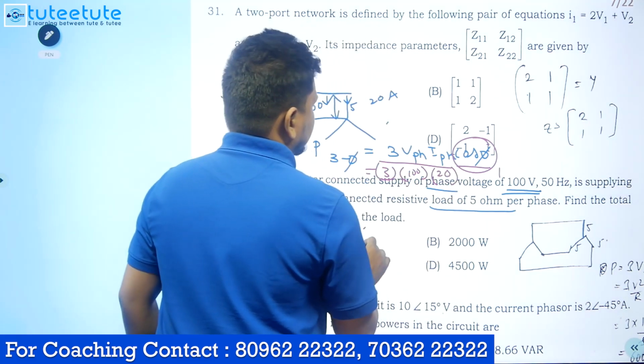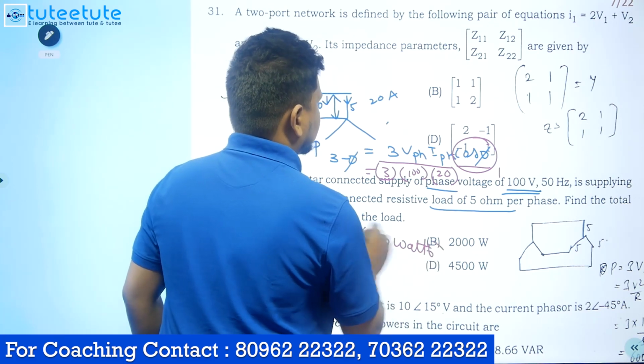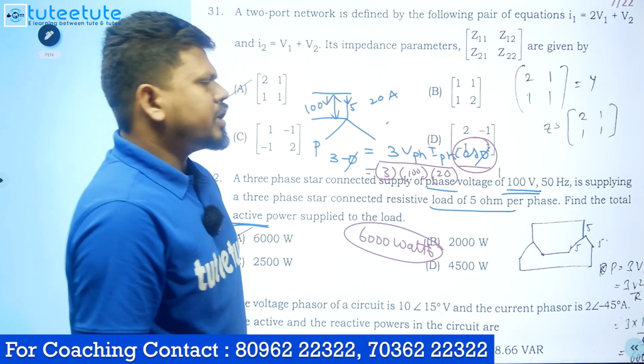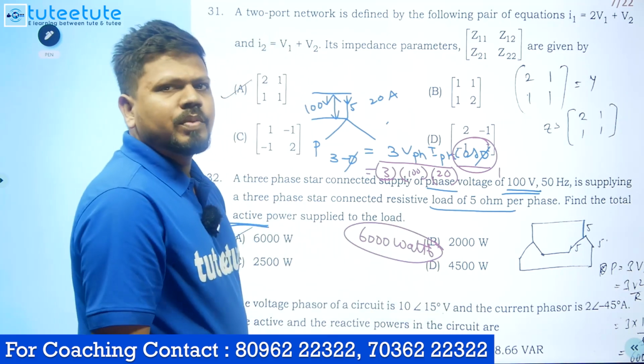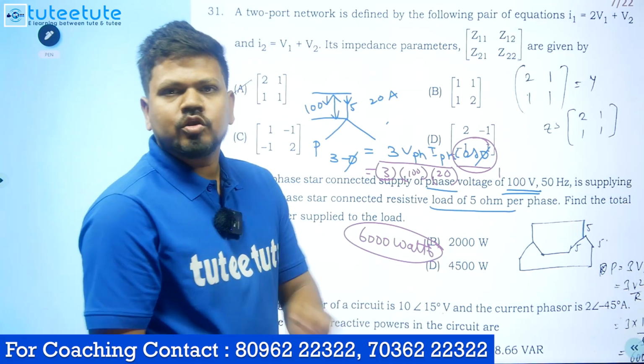Okay, so you will get 6000 watts. That's the answer. Similarly, we can find out reactive power also, you can find out complete power, but this is a resistive load, right? What is the reactive power? 0, directly, no need to check anything.